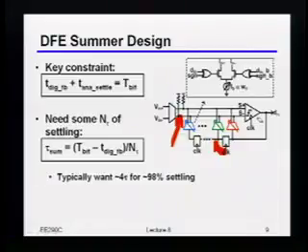Comparator. Yeah, I'm making a bit decision, right? Exactly. So do I care if it's nonlinear at that point? I'll be a little bit careful. I only care in the sense that it'll change my amplitude, right? So it'll make my amplitude a little bit smaller, but as long as my voltage margin with that degraded amplitude is good, I don't care.